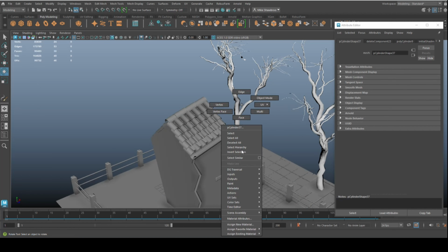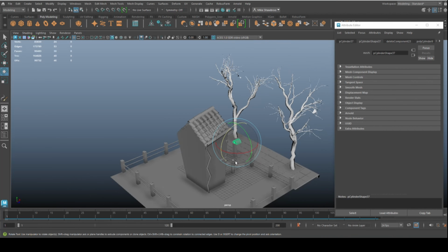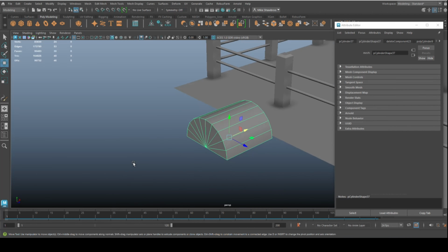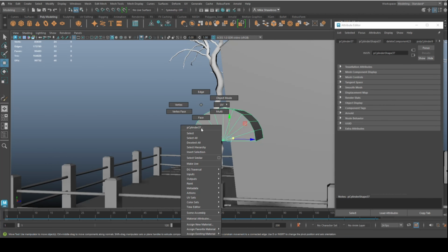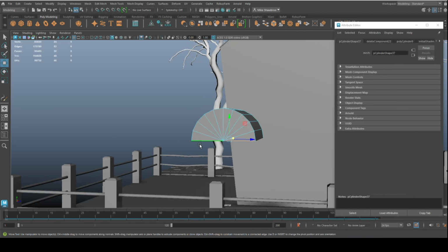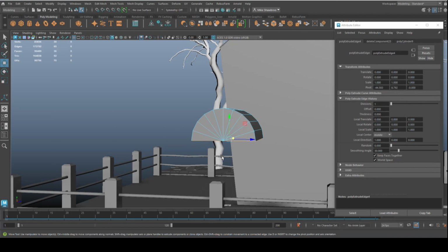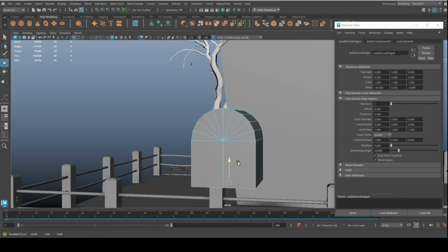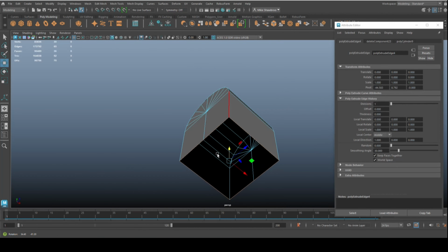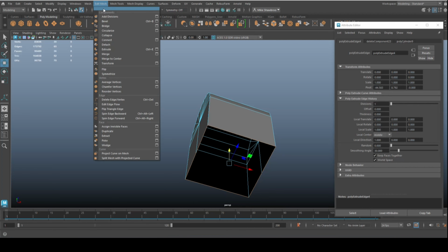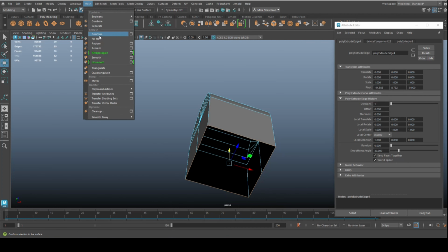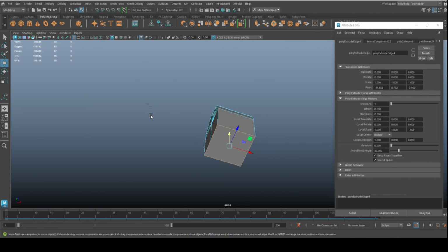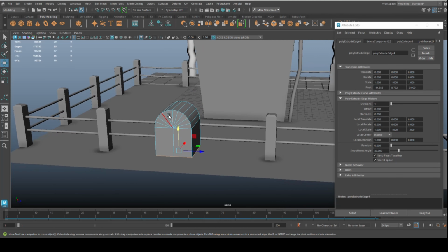Let's get this thing in the open so we can work on it. Okay, F to frame. Now we're going to go in here, go to edge, Control E to extrude, W to push down. We're going to go to mesh and fill hole to close up the bottom.